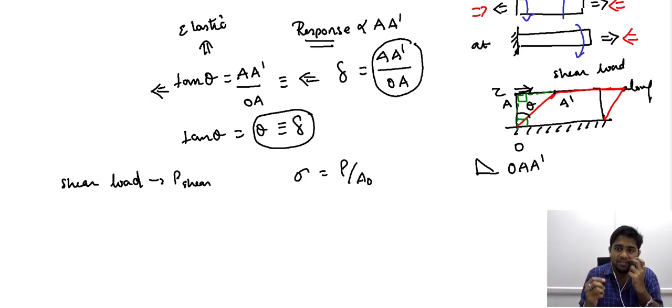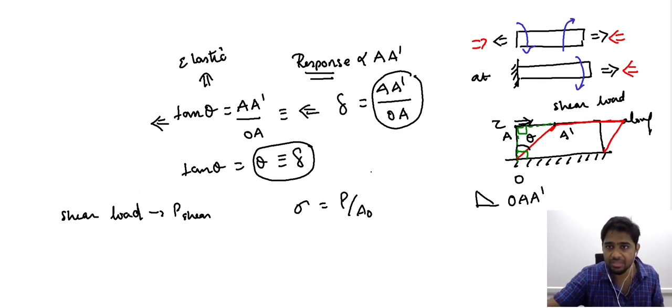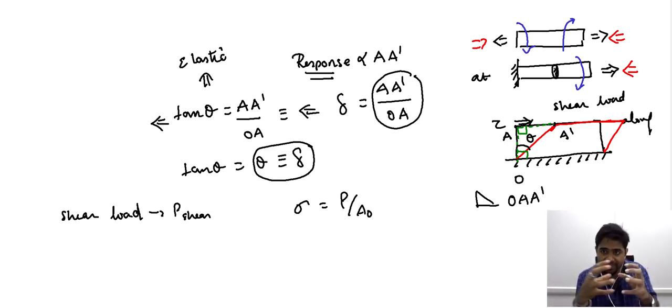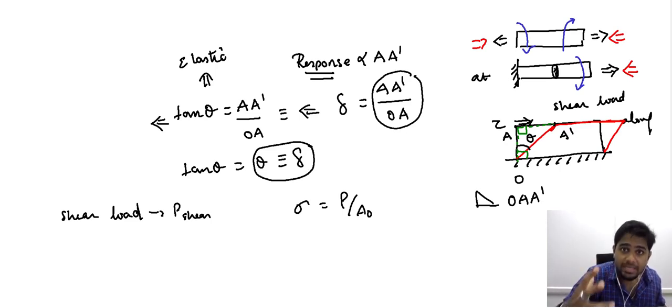Now the reason why we consider the cross-sectional area is primarily because when we impose a loading condition, let's consider the tensile loading condition, the resistance offered by the material is dependent on this cross-sectional area here. So let me repeat, when you impose the tensile load, the resistance offered by the material is dependent on the cross-sectional area. Meaning, when you increase the cross-sectional area, correspondingly the resistance will also increase. Why is it dependent on the cross-sectional area?